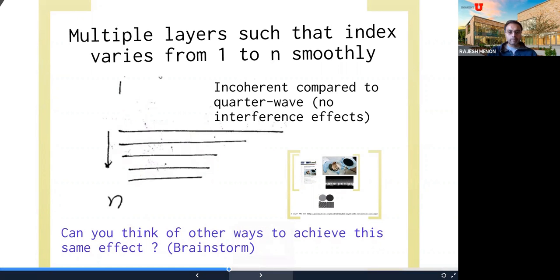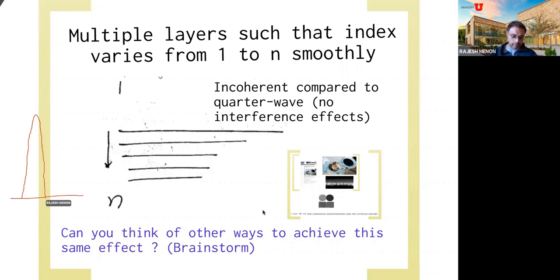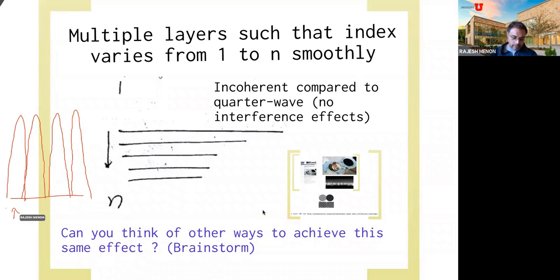A very clever way people solve this problem, and I'll show you some examples, is to make really small pillars, which are pyramid shaped or conical like that. Now let's think about why this works. If I start at the very bottom here, think about this distance as being much smaller than the wavelength of light. If I were light traveling from top to bottom, at the bottom, of course, I see the full index N. But as I start entering this pillar region, what happens?